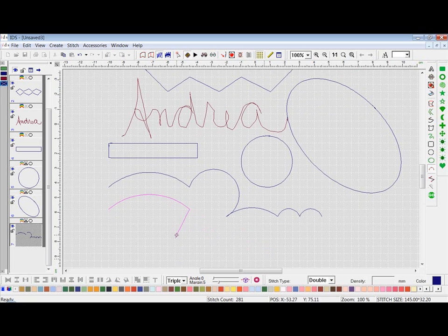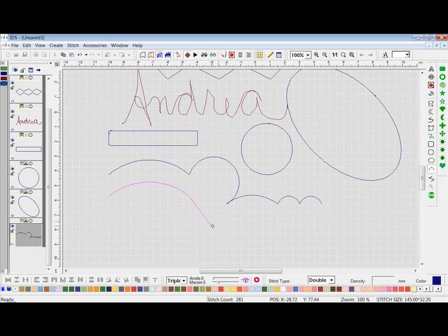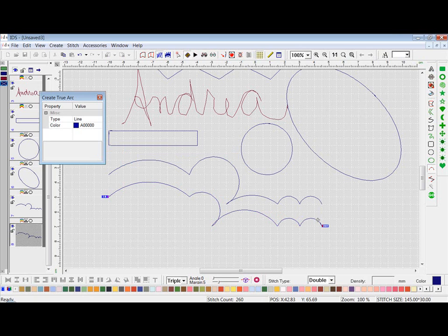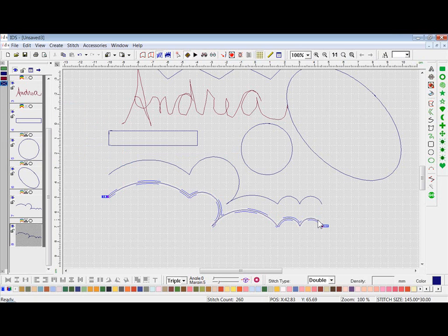And then we go to the next segment. If we'd like to do the endpoint first rather than the center point, we then do a right click, arc it, and then left click. Then a right click and a left click, repeating. Enter to end inputting and escape to get out of the tool.